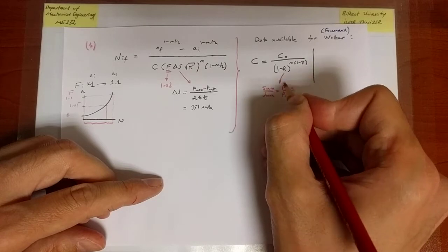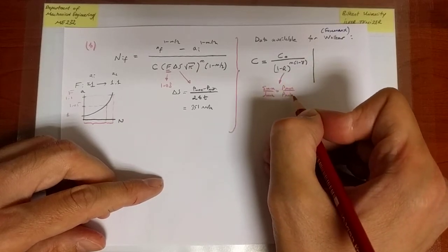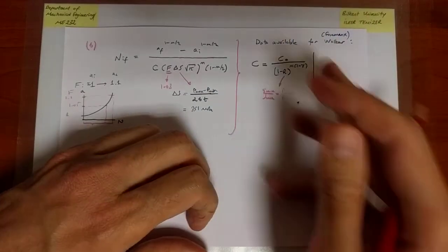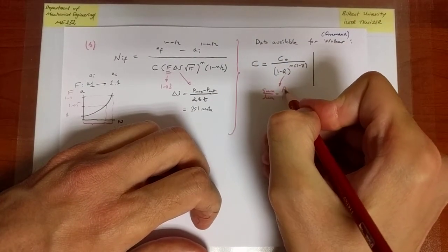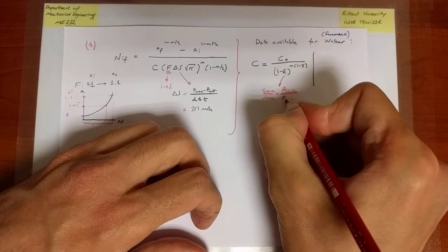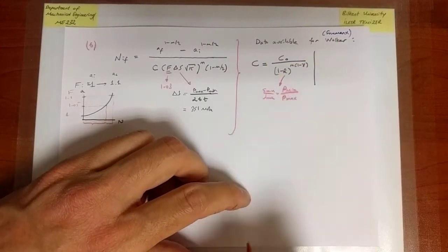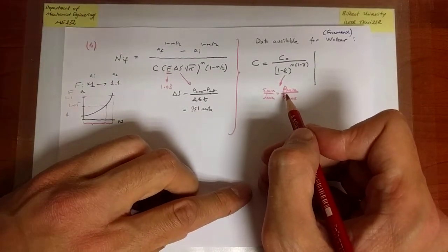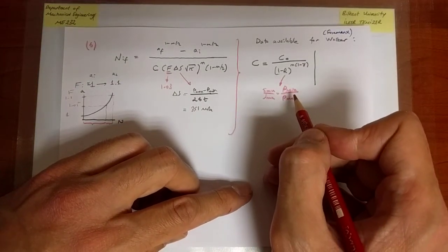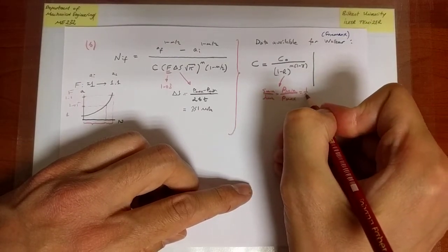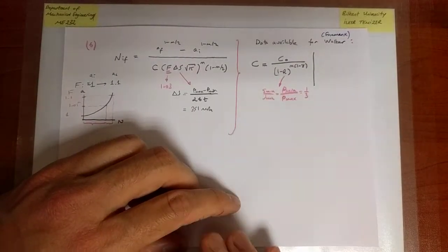Usually, the stress ratio corresponds to the ratio of the min and max associated with the loading parameter directly. It could be a tensile load. If it were a bending problem, it would eventually be the ratio of the bending moments, min and max values directly. So P min over P max, in this case, one of them is 80, the other one is 240, so it is equal to 1 over 3. So R is out of the way.